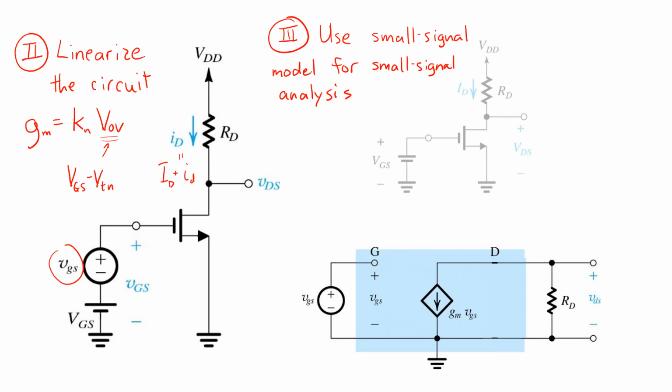So all the DC independent sources in our circuit can be set to 0. Now in this case, there's really two DC sources. They're both voltage sources. There's all uppercase VGS. And then there's also, let's not forget, VDD. We've already accounted for that when we found ID, uppercase ID here. So that can also be set to 0.